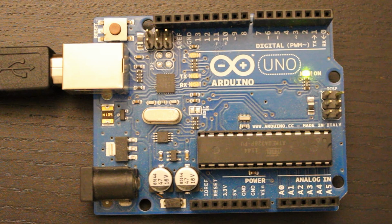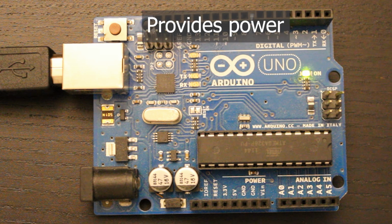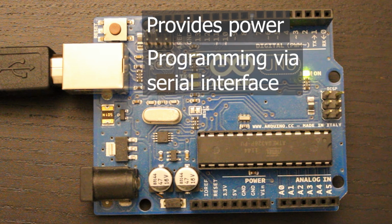Now, one thing you won't find on the Arduino Uno development board is an HDMI connection for an external display. There is a USB Type B connector, but you won't be plugging a keyboard into this. Instead, you'll use it to connect the development board to your PC. This achieves two things. One, it supplies power to the board via the USB interface, and two, it enables a serial link between the PC and the board so that we can use the PC to program the microcontroller.